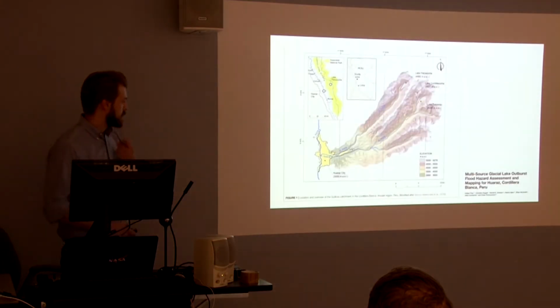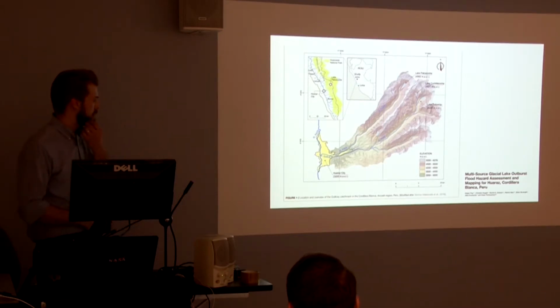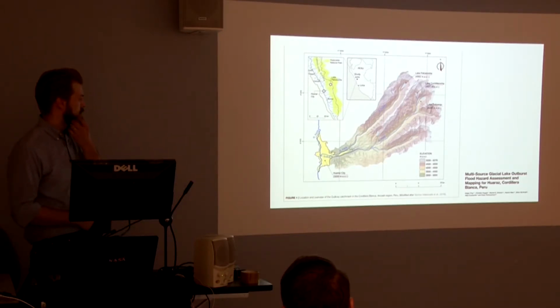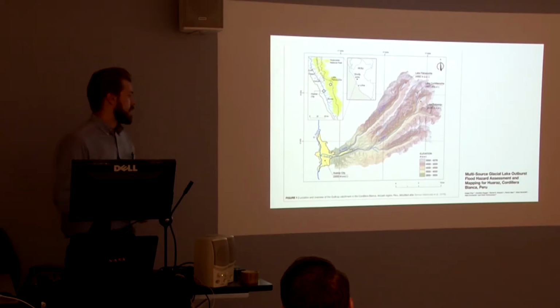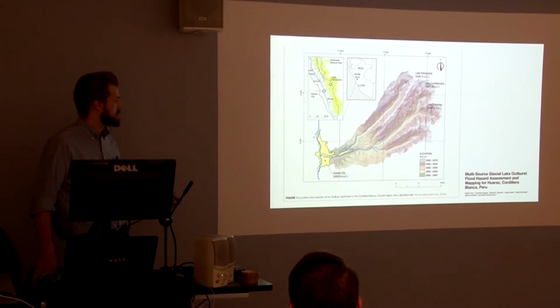And so the thing to note here, I mentioned that there are a number of heavily, densely populated areas situated below some of these glaciers and these lakes as well. A lot of my interest involves the effect of glacier retreat on slope stability in the region. As the glaciers retreat, there's a loss of cryostatic pressure, which can lead to destabilizing the ice. But there's also this risk of ice avalanches or landslides hitting the waterways, which can then trigger mass movement down these narrow valleys into the populated areas.